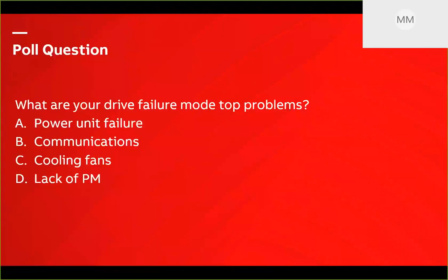Those would be some of the top failures tech support gets. Cooling fans, there's an age to all of them. The last several years we've gone to high efficiency fans, so the bearings last longer. They can get quite a few more hours out of them.